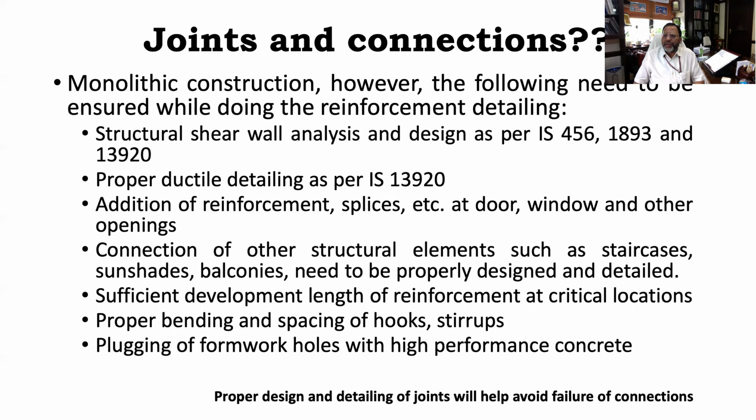But when you are doing it in a seismic zone, India is a country prone to earthquakes, so it is a shear wall design. So remember these three codes always: IS 456, IS 13920 and IS 1893. You need to design your shear walls based on IS 456 and 1893, and you have to do the detailing per 13920. So 13920 has two options: whether you want to have ductile shear wall or ordinary shear wall, and depending upon that you can do the ductile detailing.